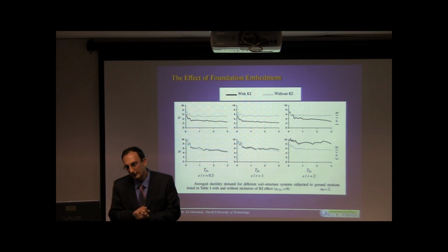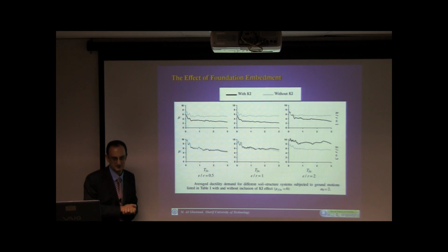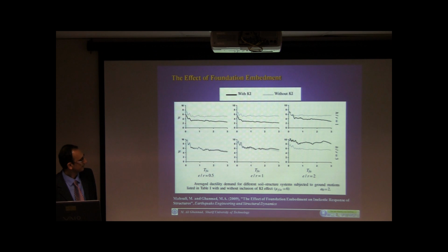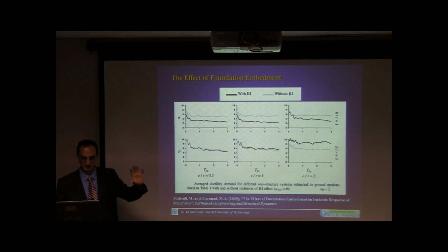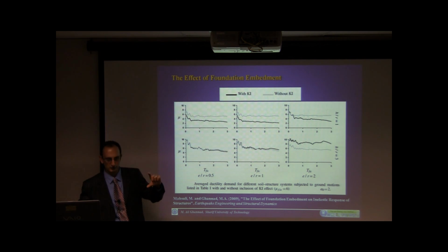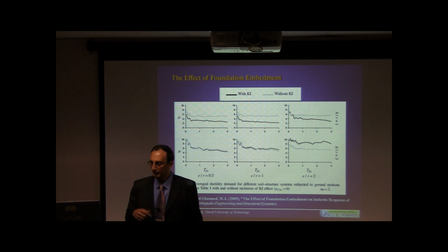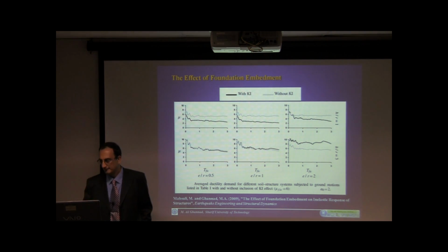Of course, in the case of surface foundation, you don't have the rocking input motion, but in this case, because it's an embedded foundation, even for the vertical, there's rocking.